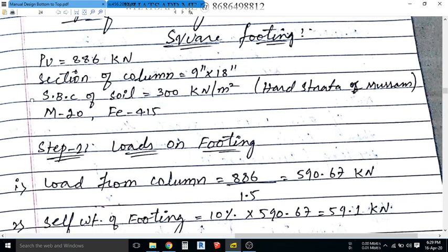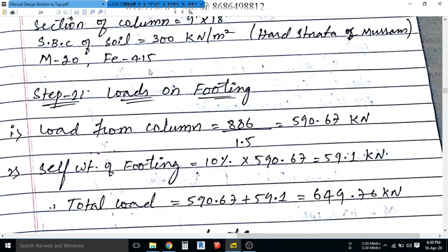Okay, now let's move on to the next step. This you will get from the soil report, and the grade of steel and concrete. You need to decide what kind of building it is, like residential or commercial, and what is the budget of the person who's creating that. But this is the standard. However, Fe415 is not the standard these days. Fe500 is the standard thing which is going on, as far as I know. However, based on your location, whatever grade of steel you're getting in the market, you have to take that. Now let's move on.